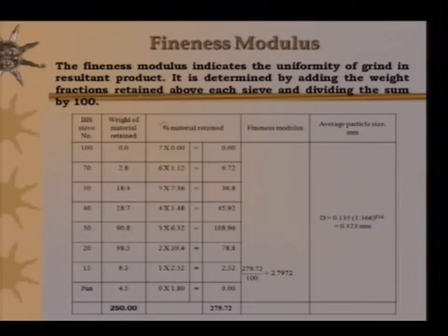Now you see here, the whole ground material is taken on a BIS sieve number 100, and then the sieves are arranged from 100, 70, 50, 40, 30, 20, in descending order. The whole lump of material is kept on the top sieve, and with the help of a sieve shaker, the whole set is shaken for 5 minutes.